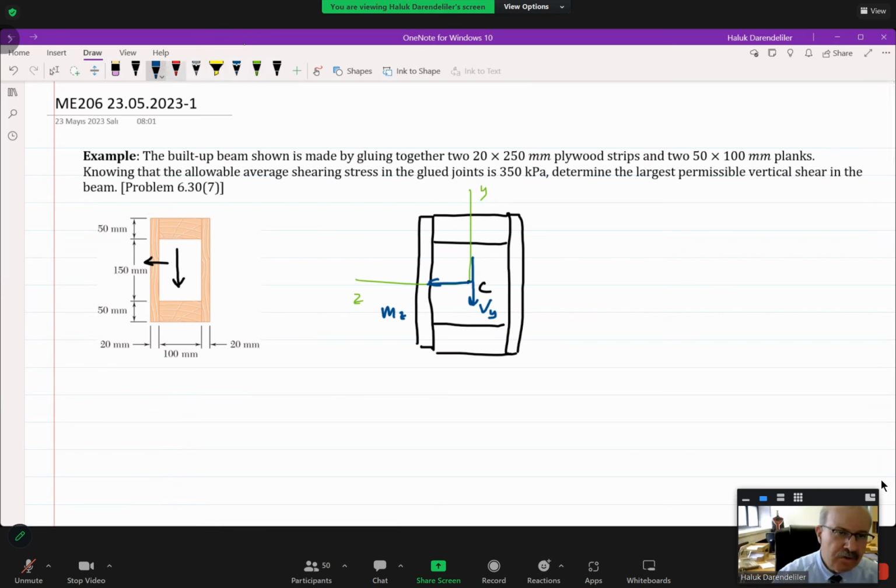Because of symmetry, look, here, excuse me, let me change the color. Here there is a glued surface, which is shown with this red line on the cross section. Here there is another glued surface. Now, remember, I said before that we have to divide the body into two for this analysis. To divide the body into two in these closed boxes, we have to use two sections. Both red lines are planes which are perpendicular to the cross section, but now they are shown by those red lines.